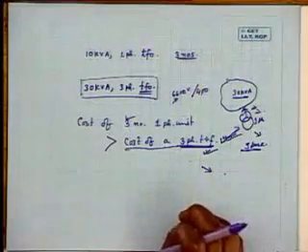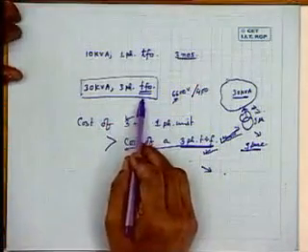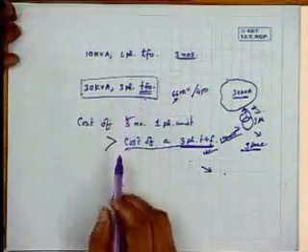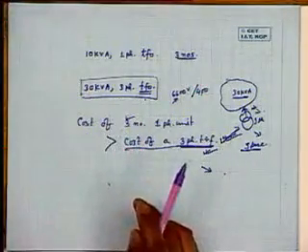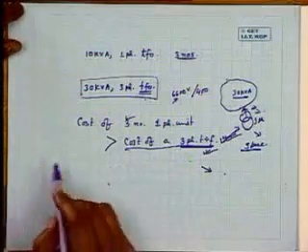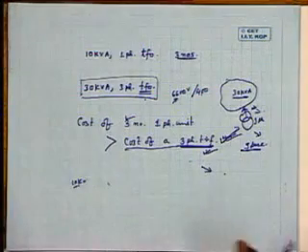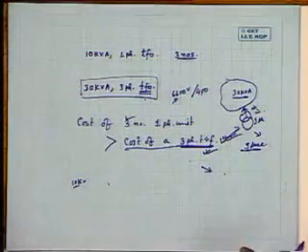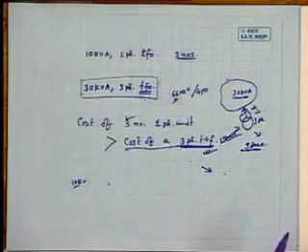So from that point of view, do you think, although the initial investment may be slightly higher with three single phase transformers, that will be a better choice? Because you connect three single phase transformers, you purchase each one of rating 10 kVA, you purchase only another as spare, because it is unlikely all the three will become faulty at the same time.